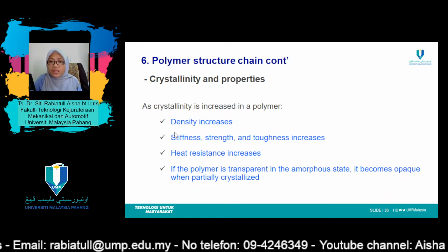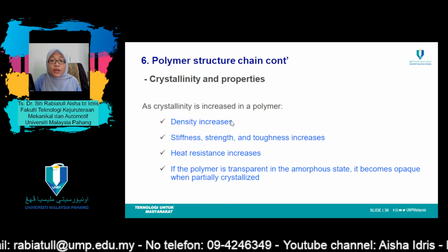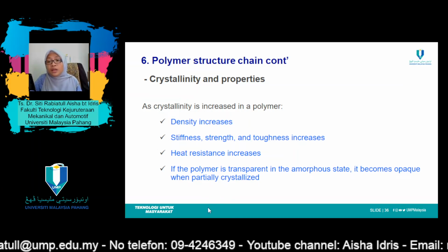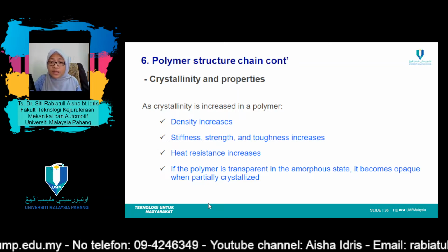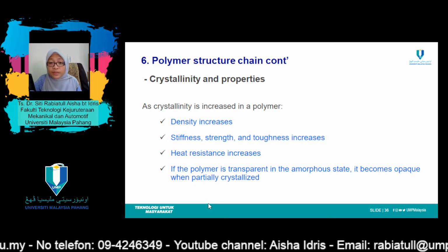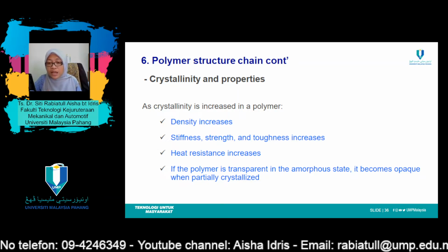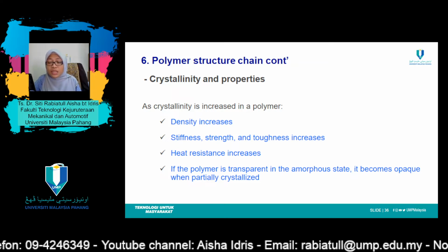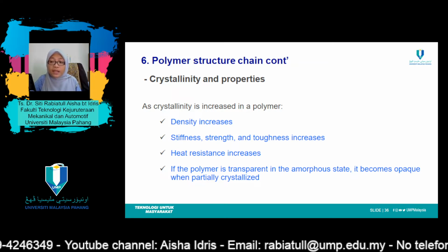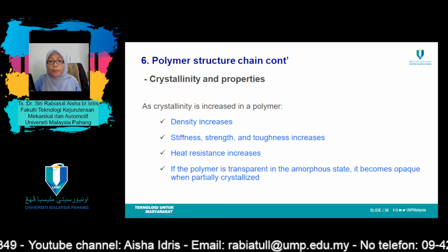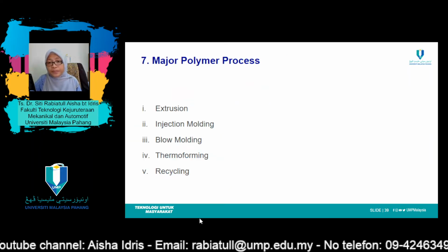As crystallinity is increased in a polymer, the density increases, stiffness, strength, and toughness increase, heat resistance increases, and if the polymer is transparent in the amorphous state, it becomes opaque when partially crystallized.